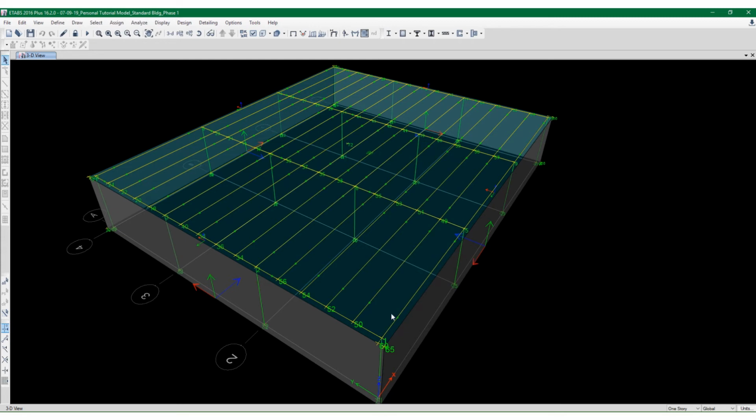this metal deck along the edges, as it protrudes away from the center line of the beam, is a deck that cantilevers out 12 inches, for example, from the center line of the beam. We would normally have a plate in that situation along, if you will, the weak axis of the deck span.